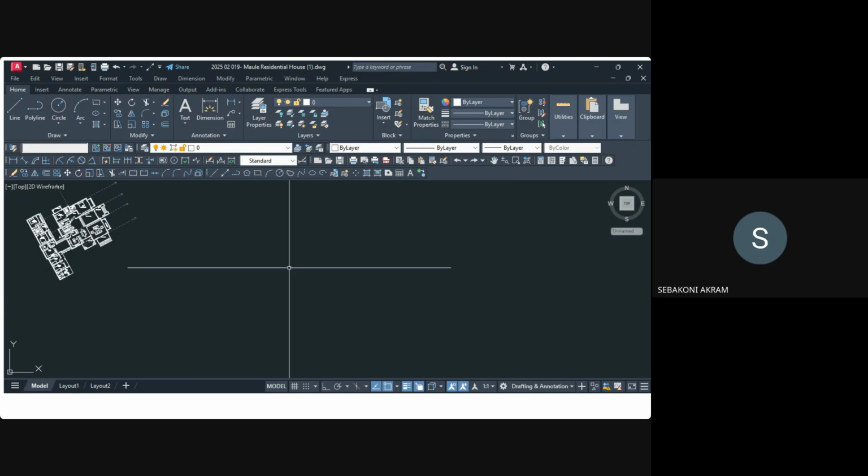So we've deleted that. So a shortcut to delete all those other things, you type... I think you're noting the commands I've used so far. We've used the burst command. We've used the explode. Panning, purging, explode, the burst. Now I'm typing in another command, which is layer delete. It's called layer delete. It deletes layers. It forces them to be deleted.